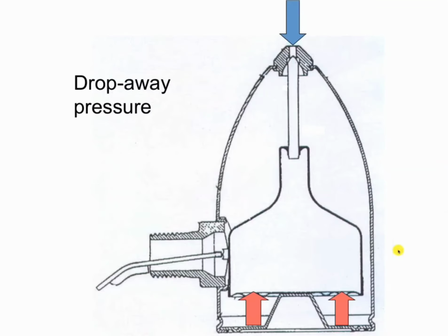All right. So I've given you the breakdown on what type of systems you can run at a lower steam pressure as far as the cutout. What type of boilers? I've given you the breakdown with large commercial Scotch Marine boilers. You don't want to set your cutout any lower than 5 psi. There's a reason why the engineers who install these boilers set the cutout to 5 psi. It's going to be roughly between 5 to 7 psi. I've given you the breakdown on that. You should respect those rules. Because if you start doing something else, you're going to start running into different problems. In my opinion, it's just simply not worth it.